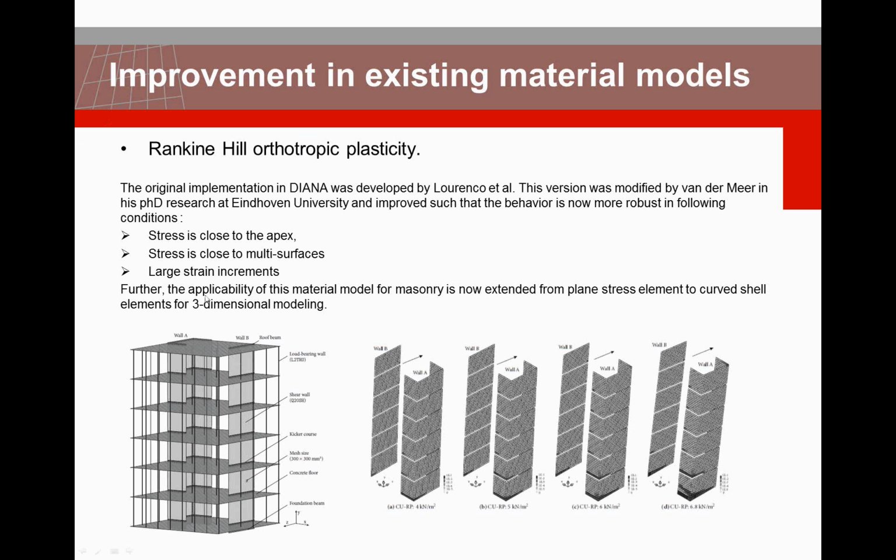This is more for the masonry structure that's modeled as a continuum, so not with interface elements for the mortar. But masonry structures are in itself very anisotropic, and that's defined with this Rankine-Hill orthotropic plasticity model. The model originally was developed by Professor Lourenço and some others.